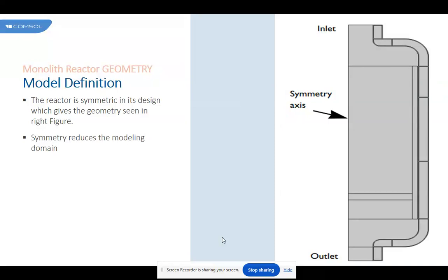Thermodynamic and transport properties. Accurate thermodynamic data is required as input to the energy balance equations, both in the plug flow model and in this two-dimensional axisymmetric monolith model. In addition to thermodynamic properties, the model equations also require transport properties to accurately describe the space-dependent reactor model. For instance, the mass transport needs specific diffusion coefficients as inputs. The Thermodynamics feature provides all necessary properties for the simulation.